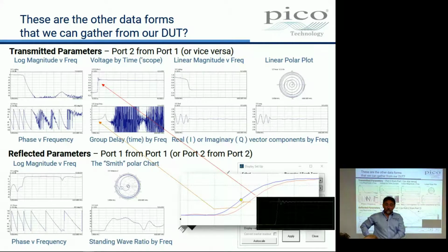If I use my mobile phone and I output data from the mobile phone, my voice in the sense of data, it goes as a modulated signal, yeah? And the modulated signal has a bandwidth. So some of the data is being encoded at these frequencies and some of it's being encoded at these frequencies in the bandwidth, yeah? If the bandwidth was that bandwidth there, some of my data would get delayed more than the other parts of the data.